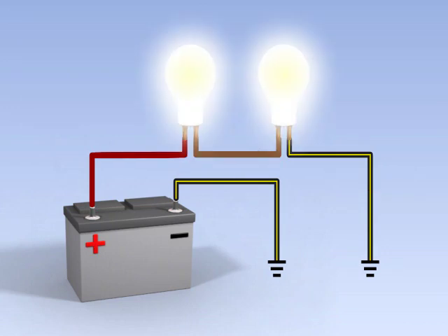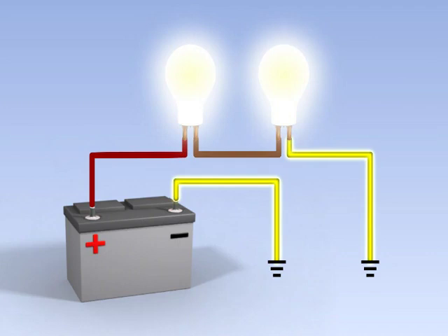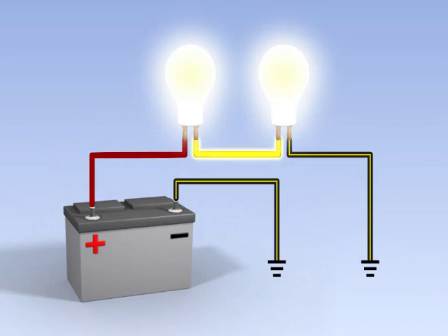It's also essential to understand that circuits have both a negative and ground side. The negative side of a circuit exists between two components and eventually leads to ground, or a common. The ground side of a circuit goes directly to ground. One special note: the color coding of the ground wires will be the same for all grounds, while the color coding on negative side wires varies.